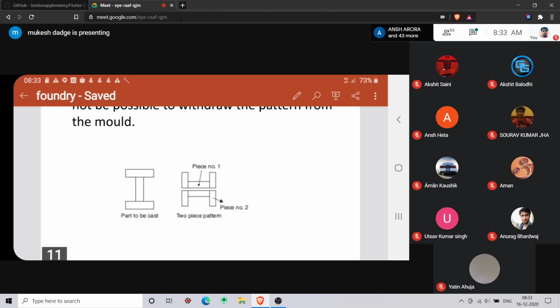It is kept in a हॉरिजॉन्टल सेक्शन, राइट। तो दोनों का अलाइनमेंट जो है परफेक्ट होने के लिए, पीस वन आप पीस टू पे एक्सट्रूडेड पोर्शन, उसको बोलते हैं डॉवेल पिन, राइट, याद रखना डॉवेल पिन। It can be asked in your viva, राइट। So how to align the two pieces in a two-piece pattern? So the dowel pin is provided in one of the parts and the hole is provided in another part, to have a better alignment.